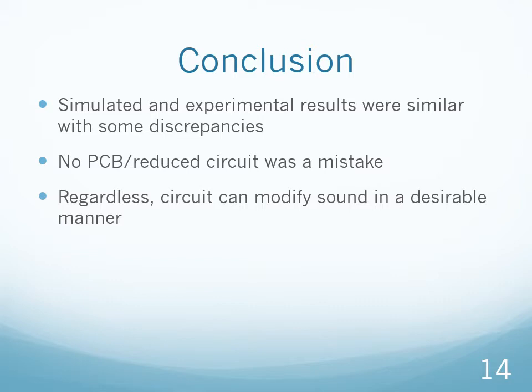When I was actually hooking it up to either my phone as an audio input or that drum machine or the synthesizer that I have, those have impedance matching in them, which I believe was messing with the levels in a way that it was doing a good job to not let my circuit overblow and make it super loud and everything. But at the same time, it was preventing the circuit, like the compression, from really having an effect until it was cranked all the way up.